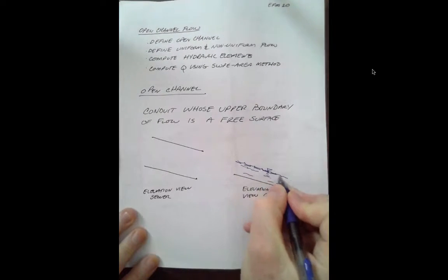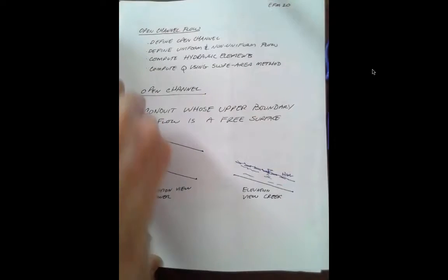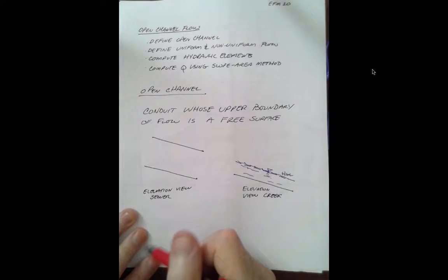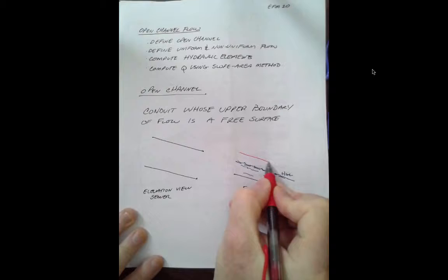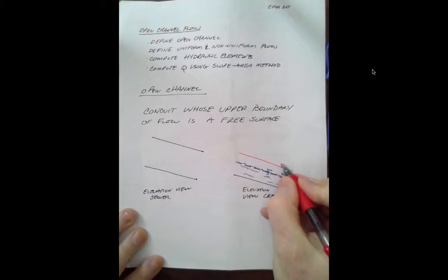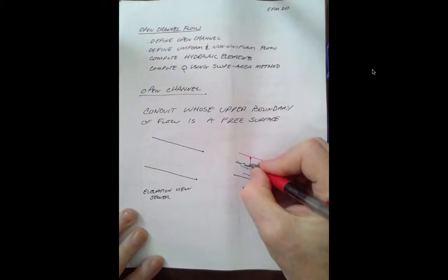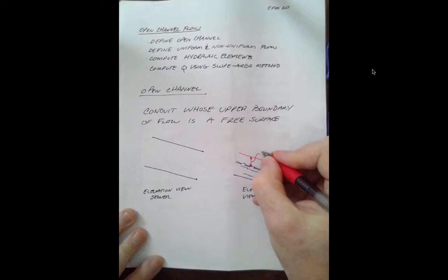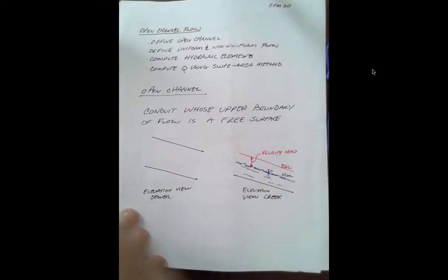So there's the hydraulic grade line for this channel, and under conditions of uniform flow, constant channel cross-section, there'd be an energy grade line here playing the same relationship as it did in Bernoulli's equation. The difference is some velocity head. And I'm being vague on purpose.